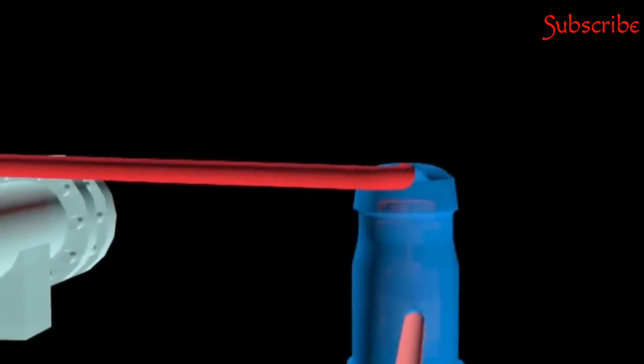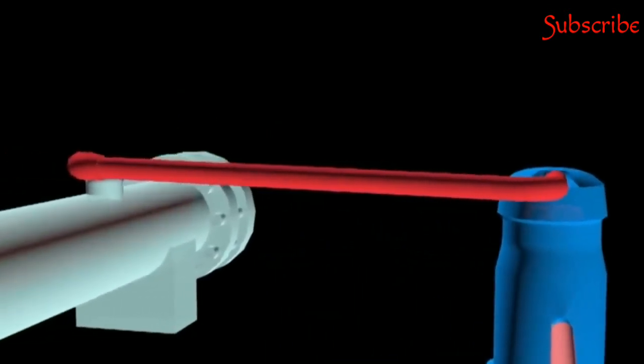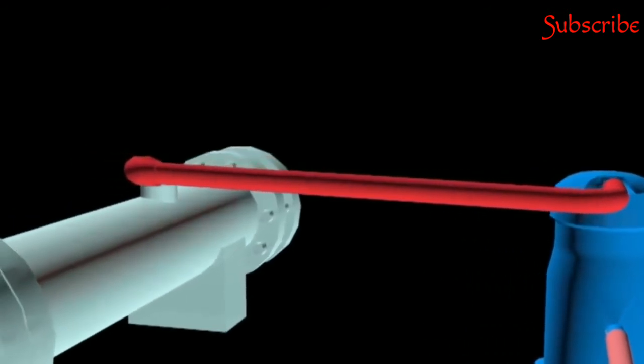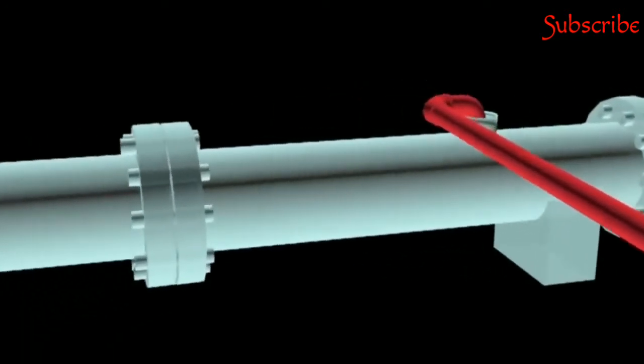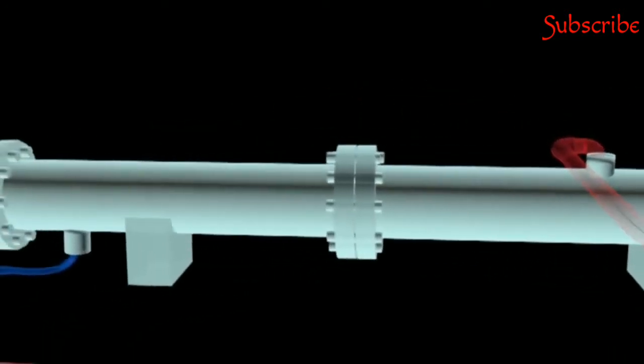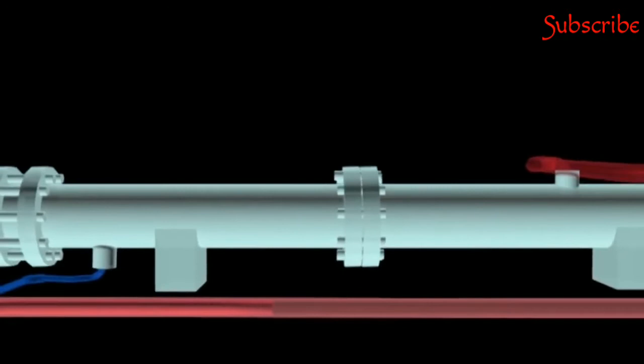Condenser. The refrigerant in high pressure gas will enter the condenser at a temperature higher than the temperature of condenser water. In the condenser, the heat will be eliminated to the condenser water from the cooling tower through the process of convection and conduction. After the heat is removed, the refrigerant in high pressure gas is condensed into a high pressure liquid when it comes out of the condenser.